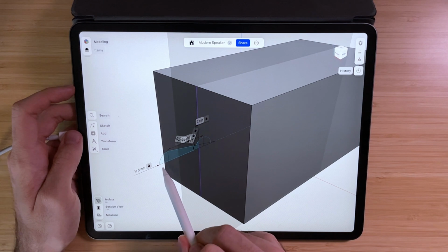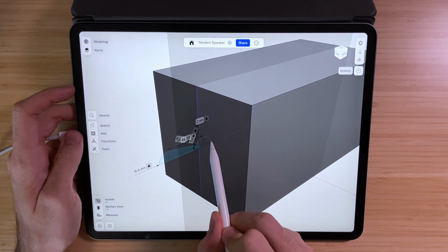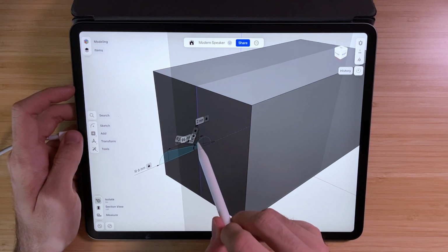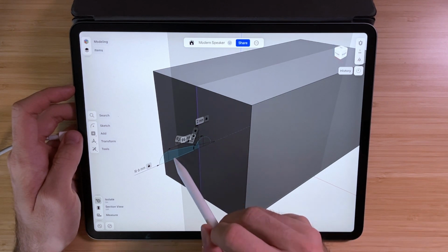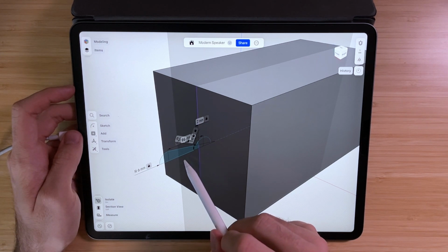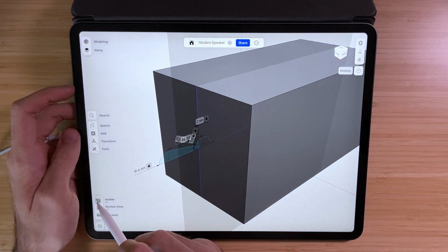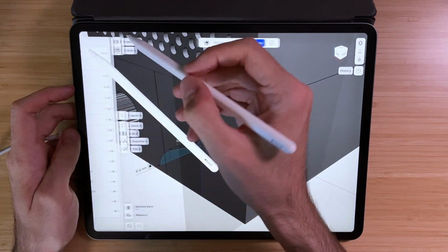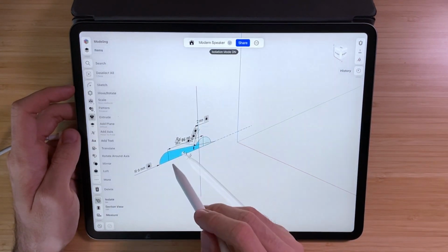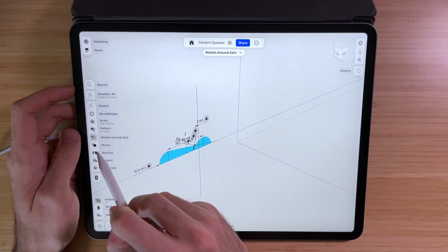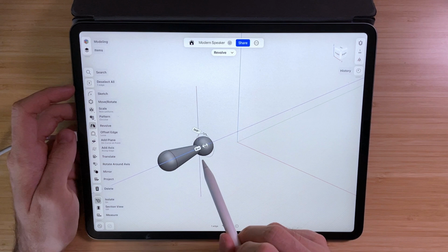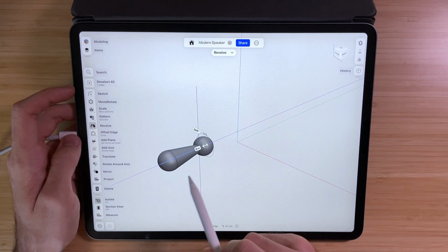Now we're out of the sketch. Let's make sure that we create a new body. Since it's intersecting with this volume, it will combine these 2 volumes as soon as we revolve it. So let's go to the isolate mode and then select our sketch. That's the only one that we need right now. So isolate this one. And now we can revolve the whole part without combining any volumes. So we'll make sure that it's its own part.